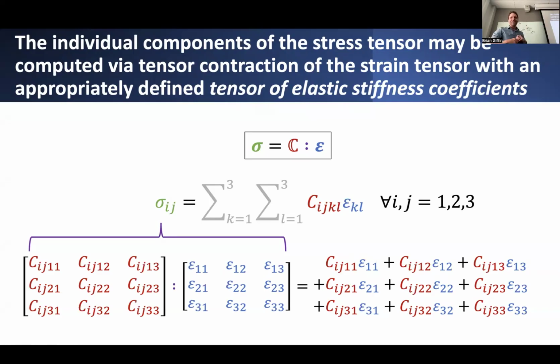It turns out that we could do that same representation like we did before. We represented everything in terms of a vector of stress components equal to some matrix of stiffness components times the corresponding vector of strain components. We can write it in that vector matrix format,